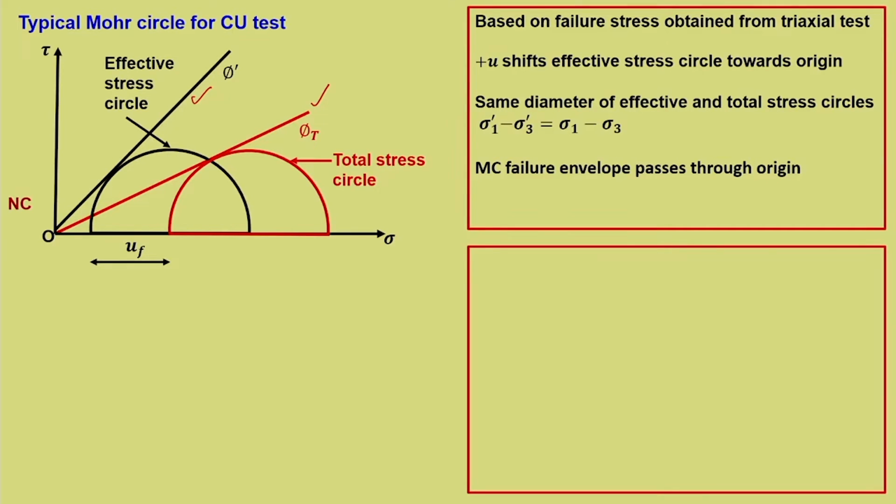Let us say that you are dealing with normally consolidated clays, and if we have a certain wrong notion that clays are always cohesive material, then we tend to question why there is no cohesion and there is only friction, which may sometimes be difficult to understand. We need to understand that all soils are granular in nature and can mobilize friction.